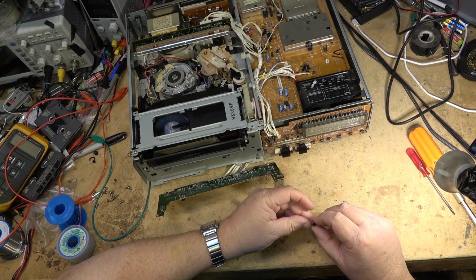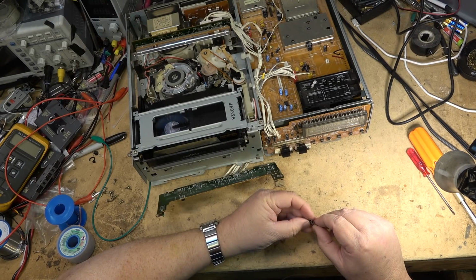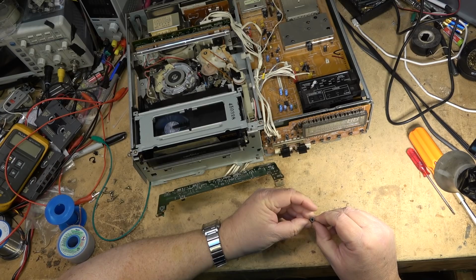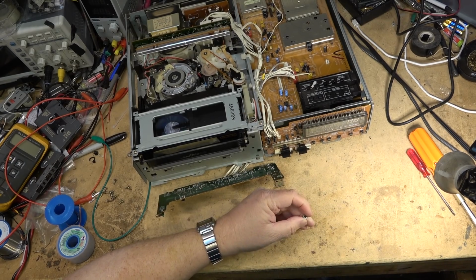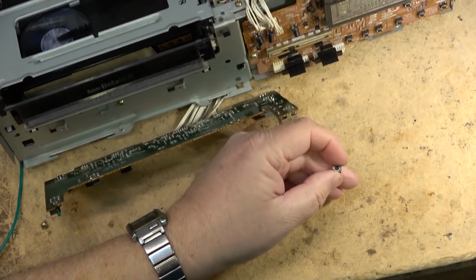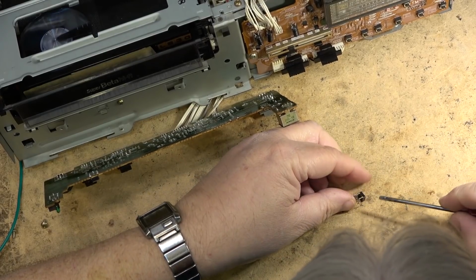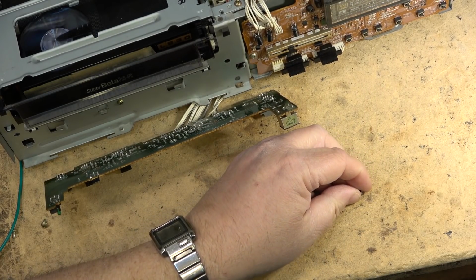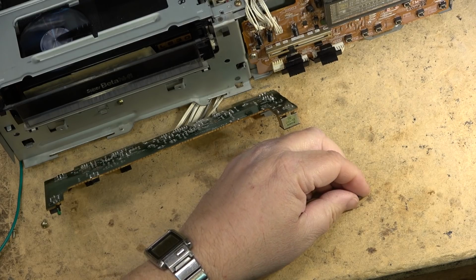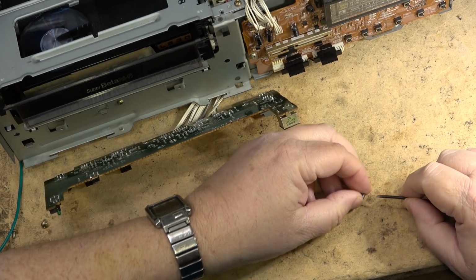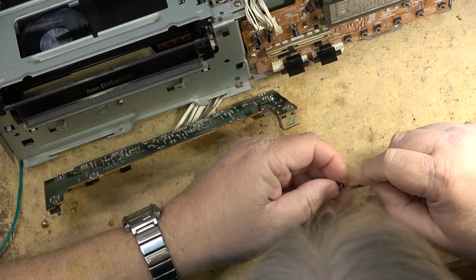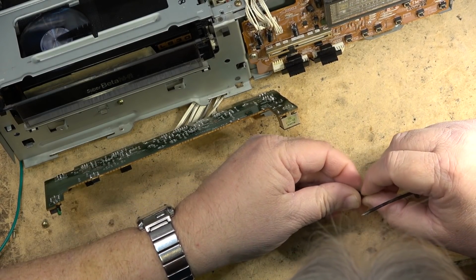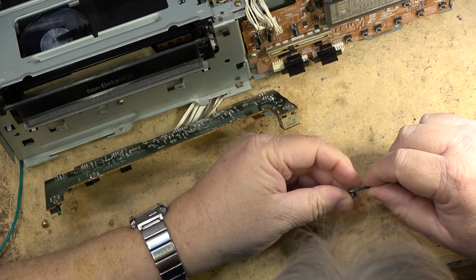Okay, this little switch is not one that comes apart easy, but we can still take it apart. I'm going to have to pop the clip off here, and underneath it's going to be a standard little button, and I bet it's all dirty and gungy, and we'll be able to clean that, I think. If I can get into this switch, which I should be able to pry my way into, we're going to have to put it back together and melt the plastic tabs over it again.